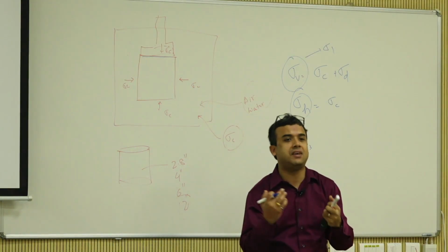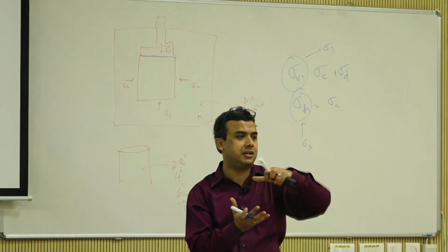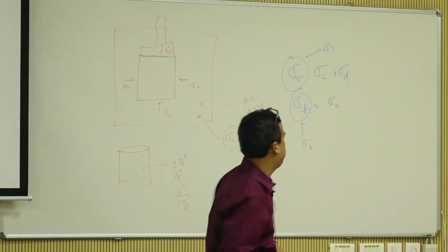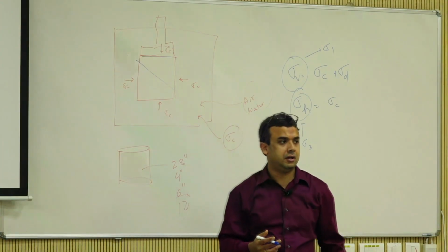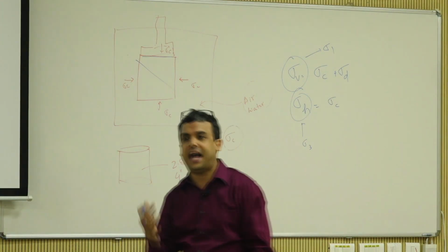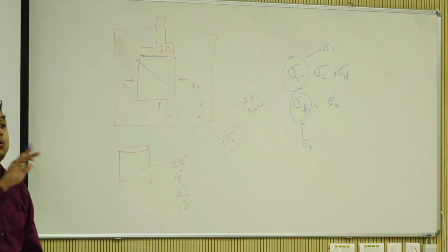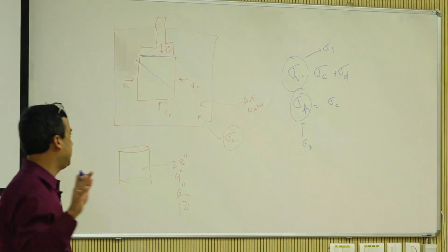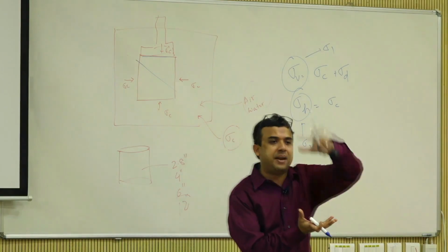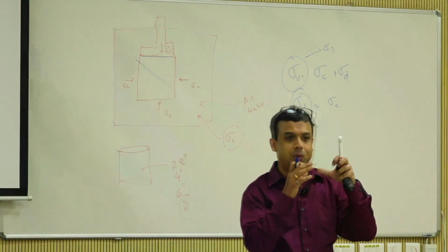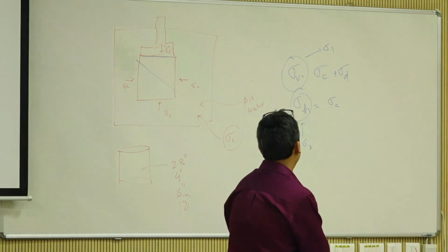So now what you can do is apply the deviator stress at a given rate, and you are going to induce axial deformation in the specimen, and then at one point you're going to have some kind of a shear failure, right? Because soils, aggregates, they always fail in shear. Even if you induce compressive loading into these things, master students, PhD students, you are actually failing in shear. So that is the reason you measure shear strength, right?